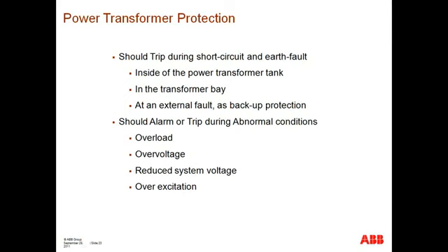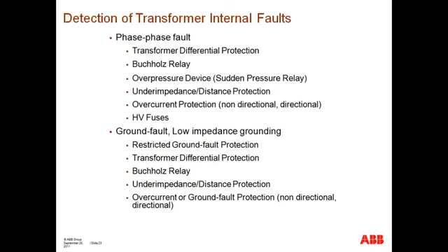In the case of short circuit protection, this is typically high-speed protection, because once a fault occurs inside of the transformer, the amount of damage is proportional to the energy of the incident. The energy of the incident is proportional to the amount of time that particular fault is occurring inside of the transformer. So the faster we can electrically isolate the transformer, the less damage, fewer repairs, and so on.